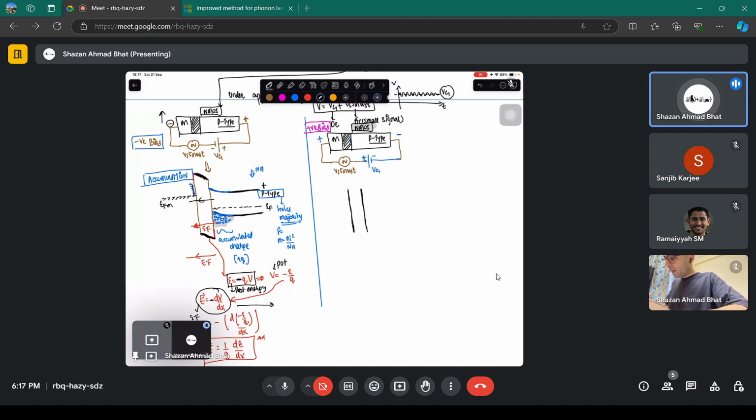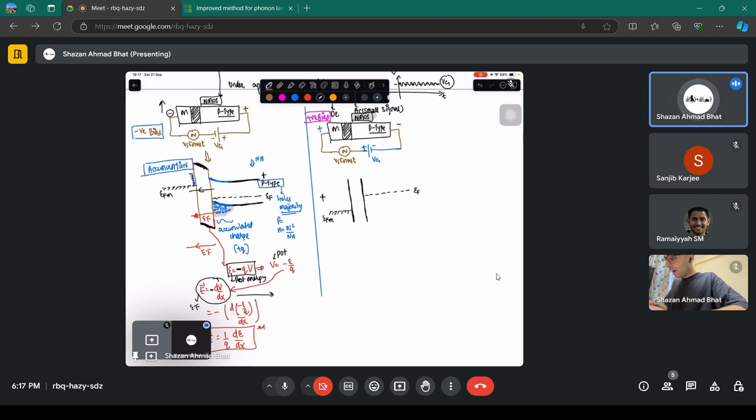Because of the positive charge, you reduce the Fermi level, you reduce the electrostatic potential energy of electrons on the metal side. Okay, this is now the Fermi level of the metal because you have applied positive charge. And on the semiconductor side, you have raised the Fermi level because you have applied the negative charge. Because you now have positive charges here at the metal oxide interface, it's as if you are taking the electrons from here and dumping them onto this side. Now, what are those electrons going to do?